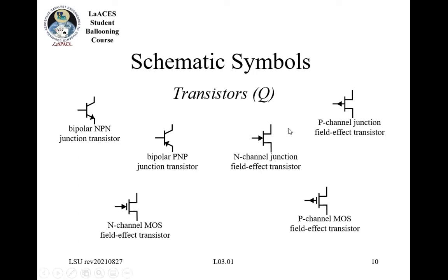Whereas a MOSFET, these are voltage control devices. So to turn it on, you increase the voltage on the gate. And when this voltage is above a defined value, the threshold voltage, the device starts turning on. When I'm saying things are turning on, it's basically when you first hook this up without the gate being turned on, this is like an open circuit right here. But once you start applying current for these devices or a voltage for this device, then these will basically become a short, and you're shorting the top to the bottom. So that's the simple way to look at it.